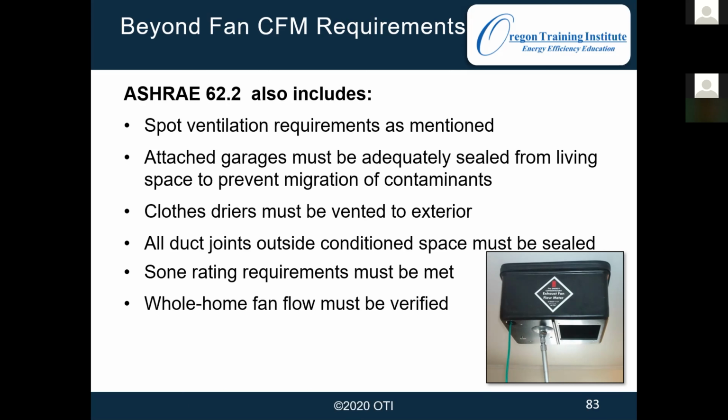We're going to have to measure the flow of the new fans. And if that is doing 2 jobs, like ASHRAE plus bathroom fan, so whole house plus spot ventilation, then we'll have to measure the 2 different fan speeds, the low, continuous, and then the full speed. And we want to make sure that our fan gets set to the proper continuous run setting or equivalent intermittent schedule.